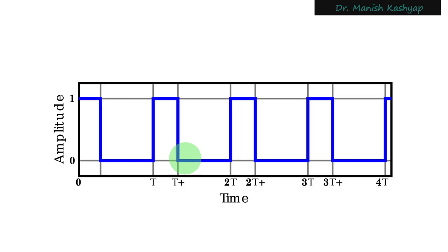Duty cycle simply means that in one period of this periodic pulse, the time for which that pulse remains on, or the T on of this pulse, is 33% of the entire period. So that's what we mean by duty cycle.